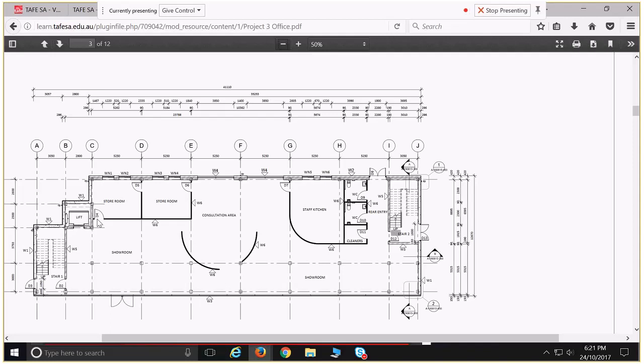The next one should relate to further out. So the next one relates to this wall here, and then that wall again, etc. And then as we move out, we also move further out on here. So we've got dimensions that relate to this wall here, like that, and then we have an overall dimension. That's the way dimensions should always be set out, and that's the way they should be read as well. So in case you wanted to get some information to interpret those dimensions, that's how we go about doing that. And for this assignment, you will have to do that as well.